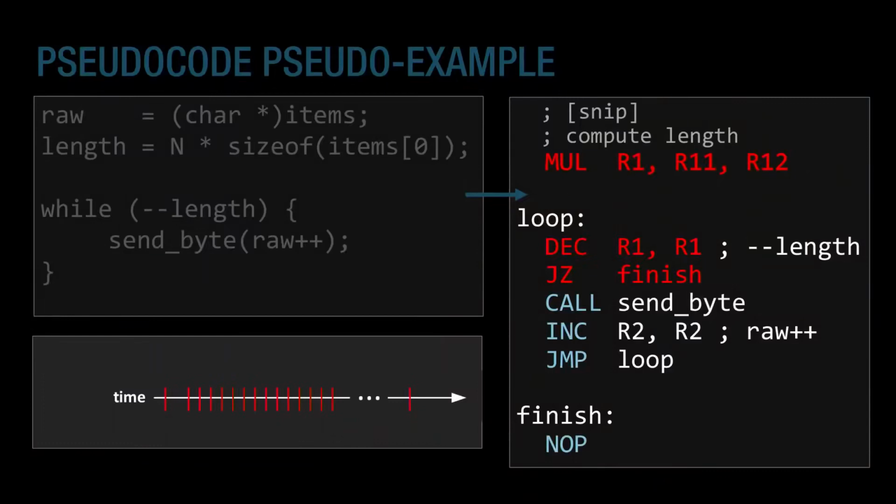Right, and so we have these opportunities that, if we're capable of corrupting values or skipping instructions, give us windows to see things past that buffer in memory. Depending on the individual device and what you're sending out, that could be transmission from read-only memory, and you could get what's next after that, which might be firmware or secrets. If it's in RAM, potentially you have other values that the device may not want to disclose, and we'll see in more complex cases we can take advantage of this to get more than just the data immediately following in RAM. But the key is that timing is absolutely critical.